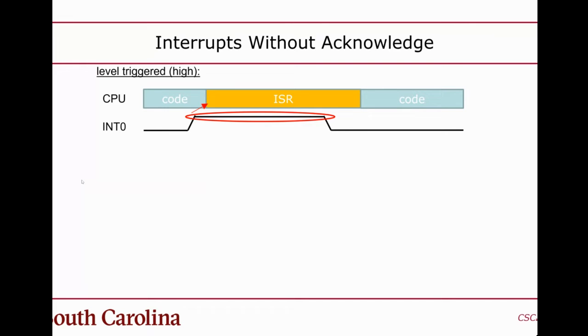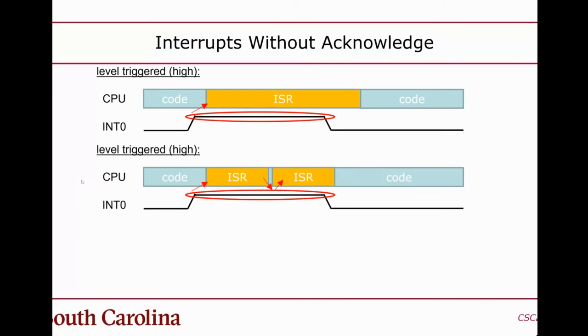Okay, so now there's a few differences. There's a couple details here that you should be aware of with interrupts. So with interrupts, I mentioned there's 1 wire for each interrupt. The wires, by the way, usually go into some sort of interrupt controller that's attached to the CPU. The interrupt wires can be interpreted in different ways. You can have a level triggered interrupt, which gets the CPU's attention whenever the level of the interrupt is logic 1 or high, for instance, or low, whatever the case may be. Or there's also edge triggered interrupts, which convey an interrupt to the CPU on the rising or falling edge.